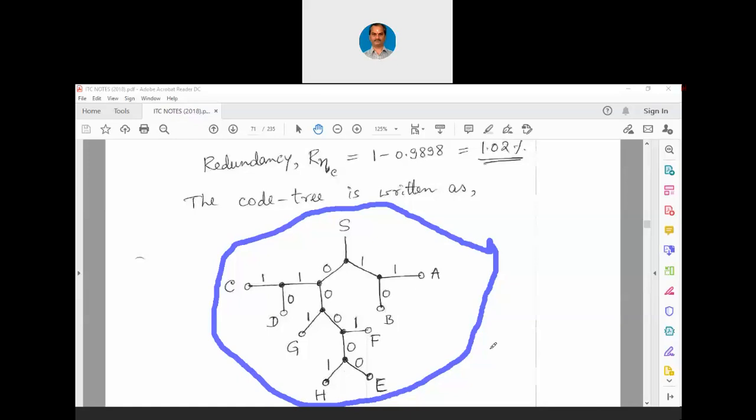That is enough. So when the codes are represented as a tree structure or a graphical approach, then we can easily put this tree diagram itself into MATLAB. If we put this tree diagram into MATLAB, MATLAB can immediately generate Verilog code. Nowadays, MATLAB is so powerful. If you give a block level Simulink model, you can actually obtain Verilog code. And that Verilog code can be directly synthesized and it can be downloaded into the FPGA kit.